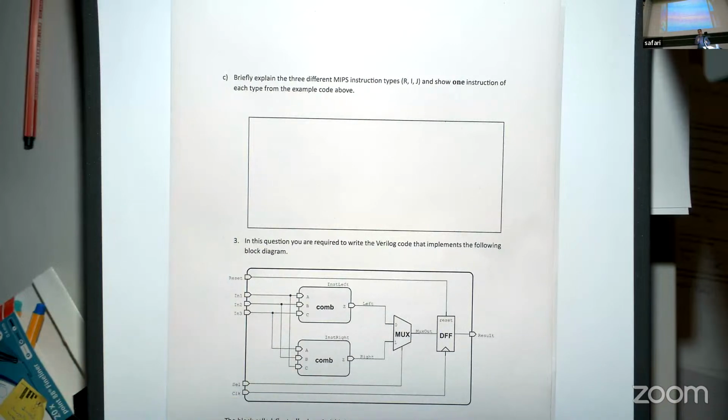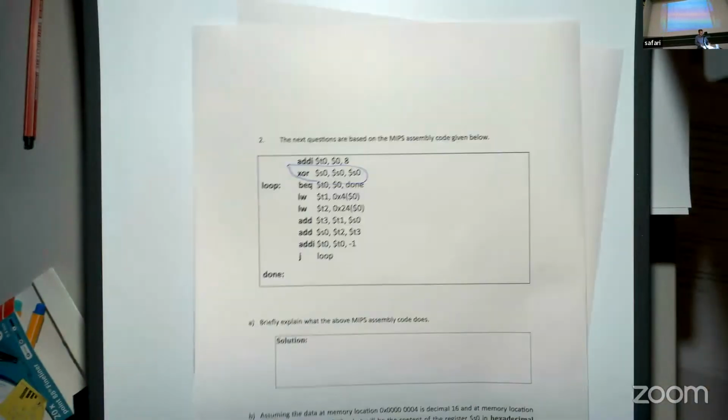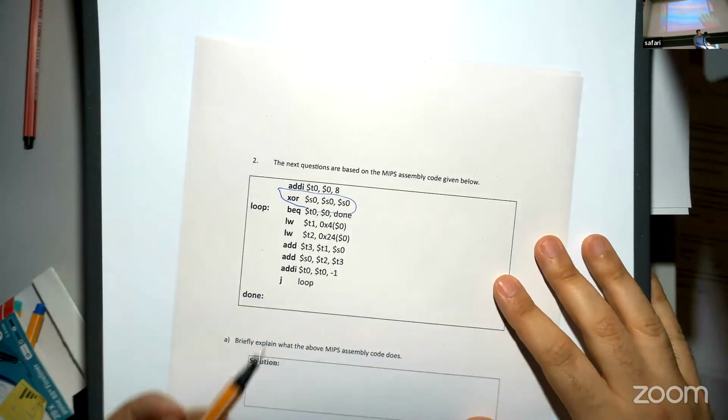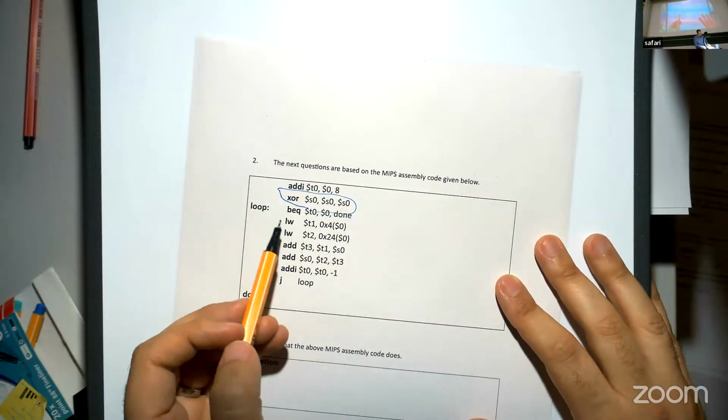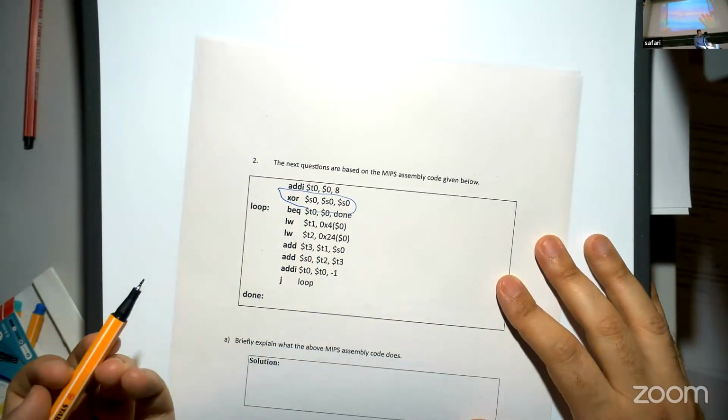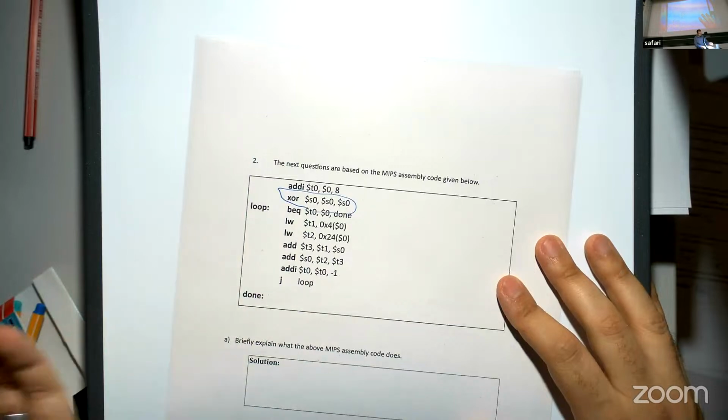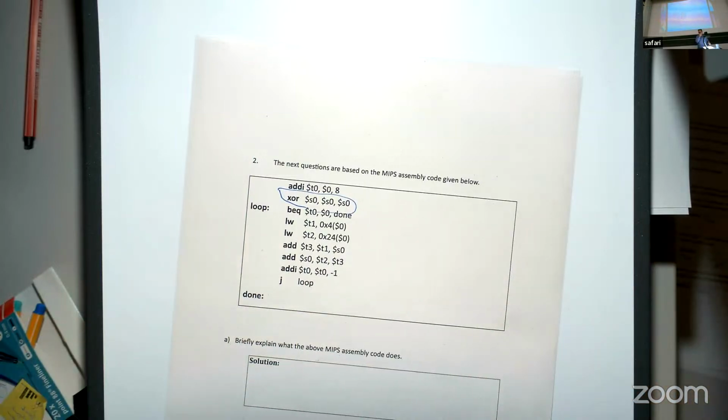Whether you want to use that immediate value for an arithmetic operation, like ADDI, XORI or ANDI, or you want to use that immediate for a branch instruction, like conditional branches, branch equal, branch not equal, and so on. That would be the answer to what I-type is. And from this code, we have ADDI, BEQ, even load word. There are many examples of I-type.